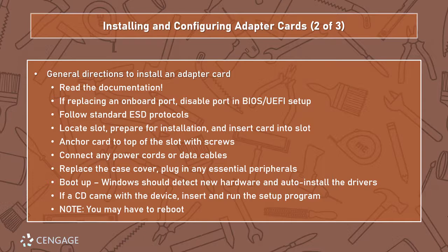Follow your standard ESD protocols, so make sure you're wearing your strap, make sure you're grounded, make sure you power everything down, discharge it, and be aware of the contact between yourself and components as well as components to one another. Locate your slot, prepare for installation, you know, clear cables out of the way, make sure that the cover on the back of the I/O shield has been removed, and insert the card into the slot.